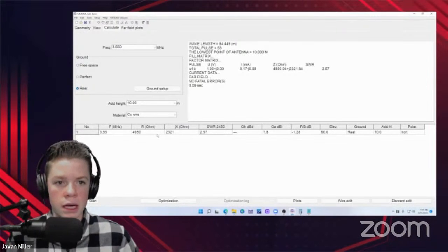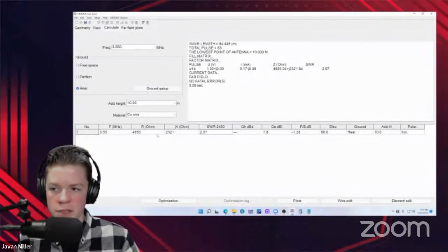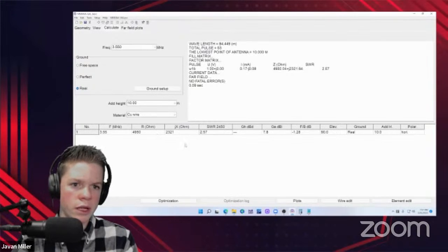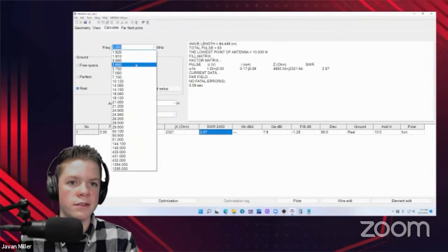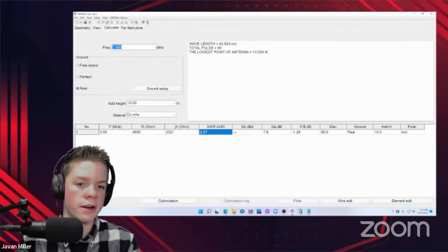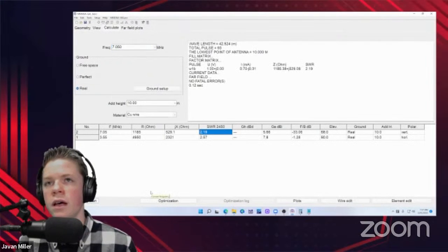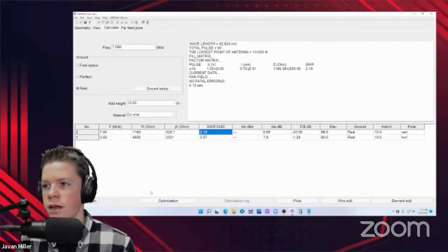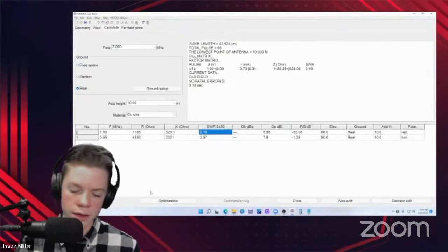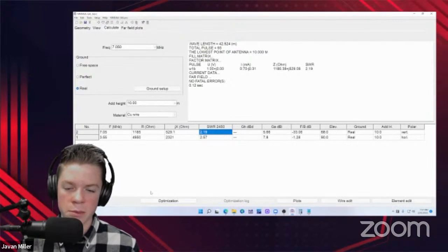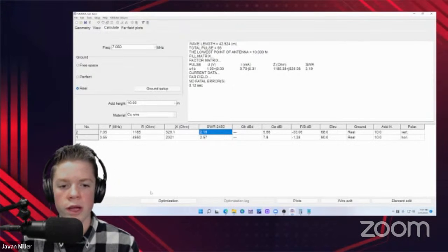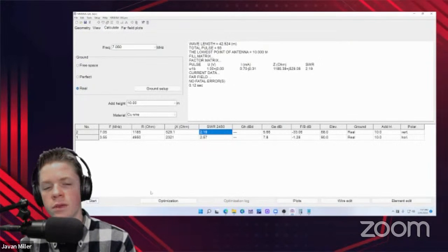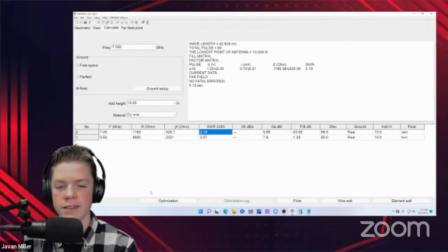But we'll look at the other bands to see what compromise we need for the impedance ratio of the transformer. Now we can go over to the other bands, and we're going to see something interesting here. Let me see how to explain this. The bands don't line up quite perfectly if you think about it. To make it an antenna that's going to be resonant, say on 14.200, about the middle of the band on 20 meters, or I guess 14.175, that's in the exact middle.